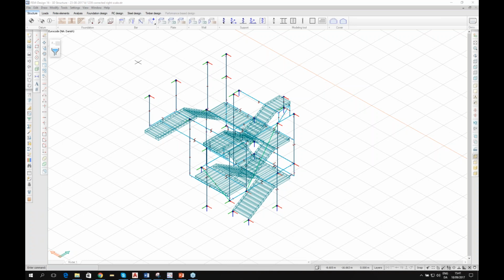And then Jakob, if a HEB beam lower flange is lying on another HEB beam upper flange, how would you make the connection? I'll always make a distance in between them, and then if you are welding it together, I'll go with a line-line connection to actually model the welding. If you're bolting it together, I would go a point-point connection from the upper flange to the bottom flange on the above lying HEB profiles.